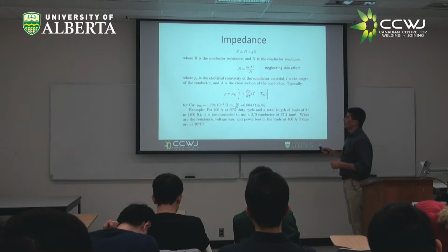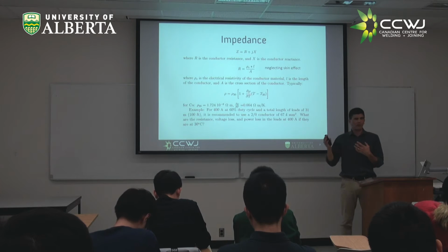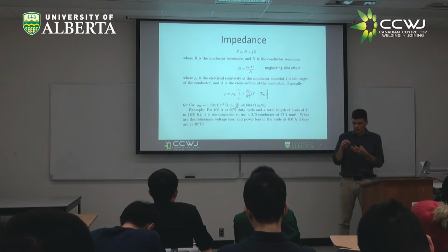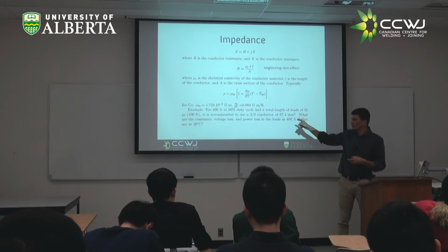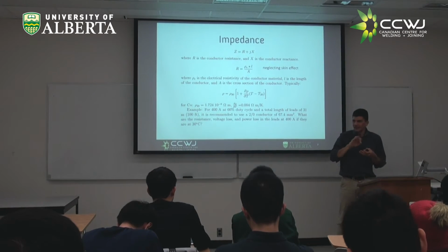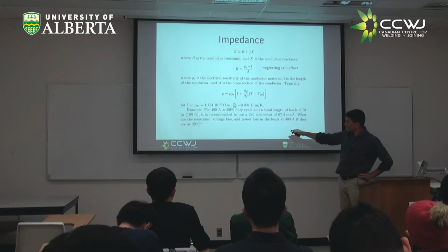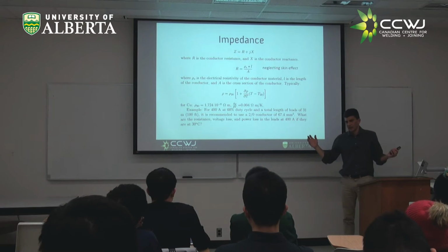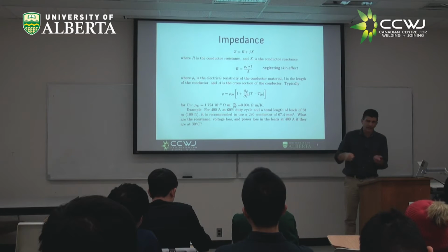So let's talk about an example in concrete. And you have all this in your notes, so I'm going to be flying over this. But I very highly recommend that when you go home, or when you prepare for the exam, the night before, whatever it is, you go over this, writing it with your own hand on paper. So let's say 400 amps, 60% duty cycle. 60% duty cycle means the welder is welding for 60% of the time, and 40% of the time is grinding or taking a bathroom break, whatever it is, right?